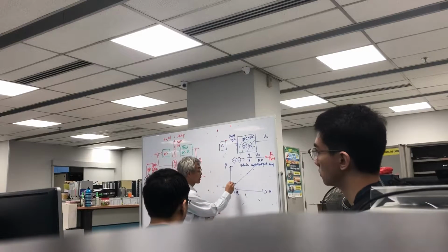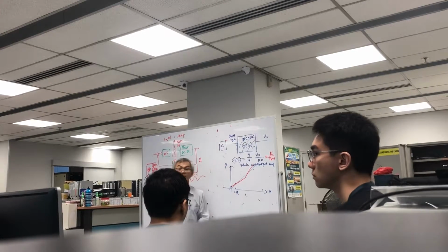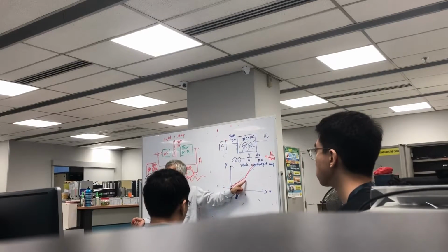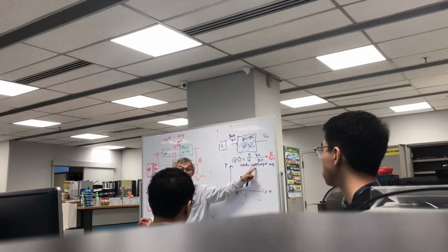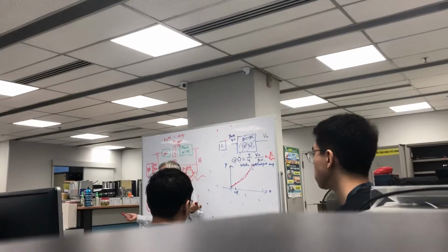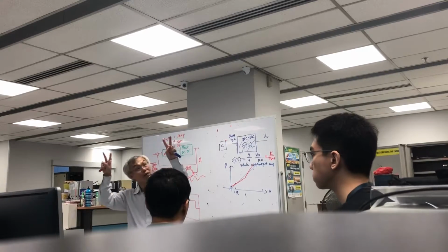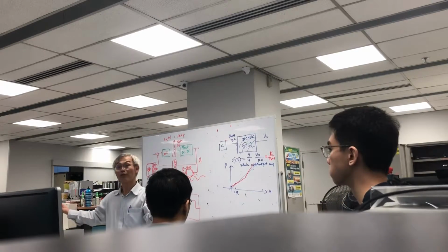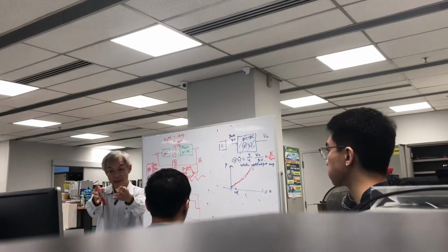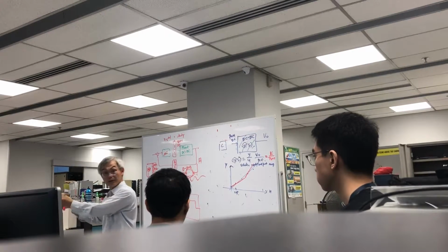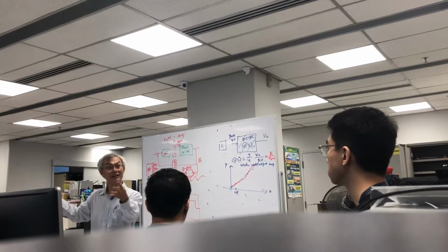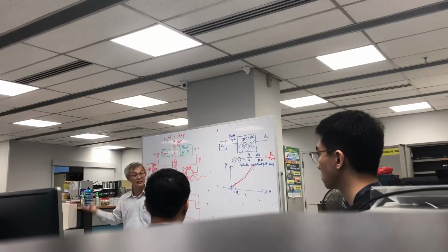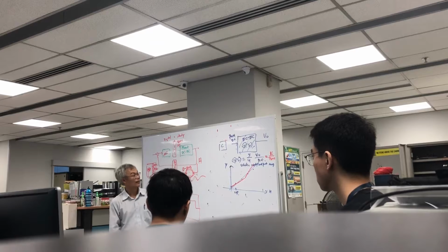Well, you may collect data and then you may get a line like this. Then you say, oh, there is a gain in this operating range, which is different from the gain in this operating range, the static gain. And that will influence your so-called controller design, right? You will have a more clever design. Now it's software, right? You will write the software. If you're operating here, then I will use this parameter. If you're operating here, I will do this. This is what the industrial say, intelligent control. Or fuzzy logic, neural network, whatever it is.